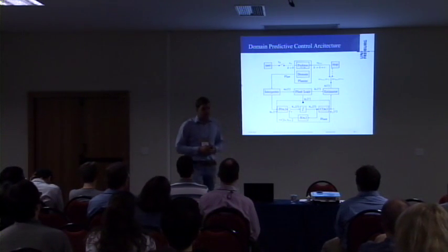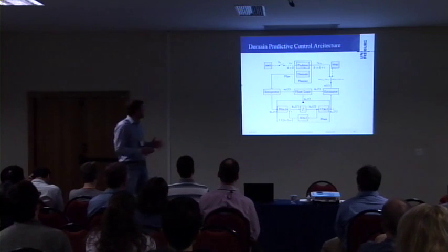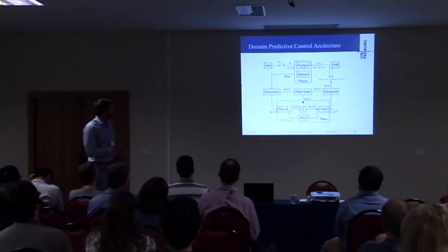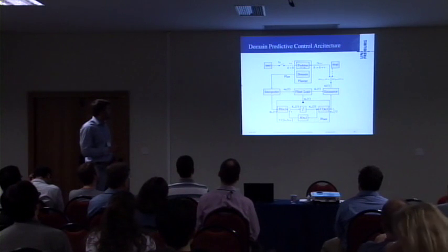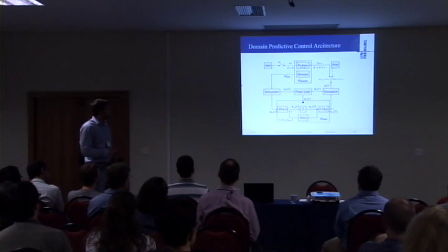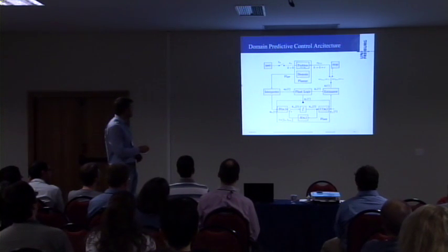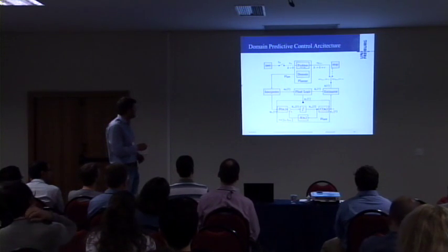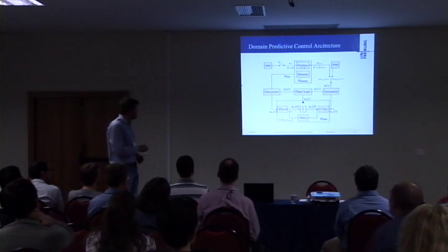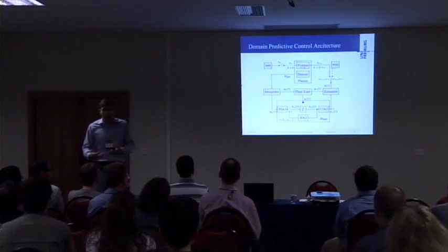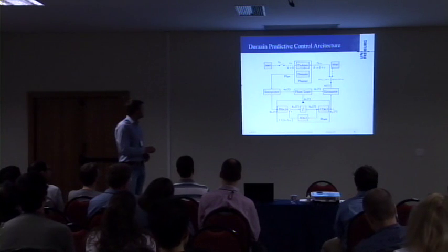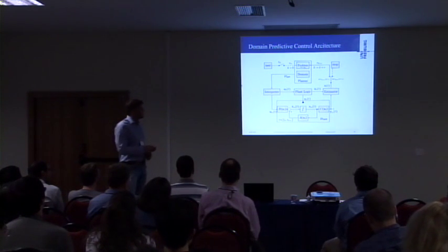And this finally is the domain predictive control architecture. Let's briefly go through the loop here. A user or an external system defines or provides some goal information, S star. This goes into the planning problem. And we receive the current hybrid system state here. The planner now starts predicting future states, generating a plan on the basis of the domain model available here. This plan goes into the interpreter, which will interpret it into a numerical input signal, for instance, a sequence of torques or forces, which will then guide the dynamic system in the direction we want.